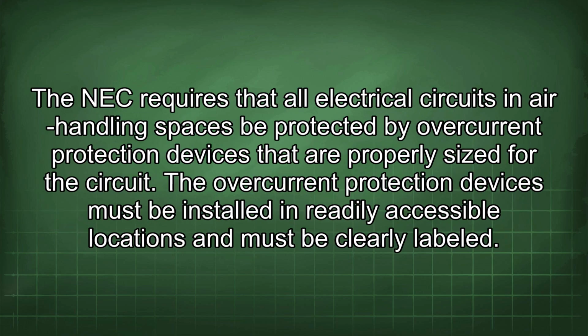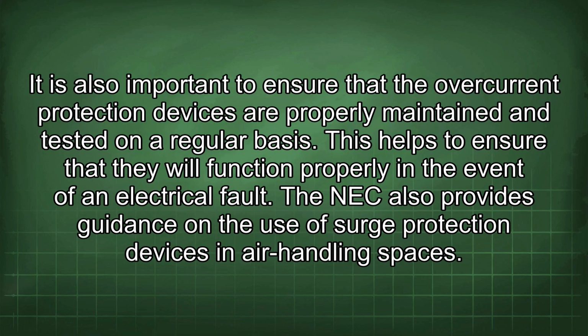The NEC requires that all electrical circuits in air handling spaces be protected by overcurrent protection devices that are properly sized for the circuit. The overcurrent protection devices must be installed in readily accessible locations and must be clearly labeled. It is also important to ensure that the overcurrent protection devices are properly maintained and tested on a regular basis. This helps to ensure that they will function properly in the event of an electrical fault.